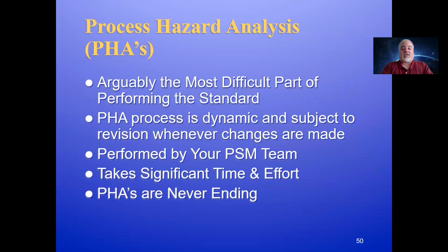Process hazard analysis. This is something that for refrigeration you don't have to worry about, because you don't have to go through and talk about what are the hazards of refrigeration. The hazard is a release, period, of anhydrous ammonia. The release is the hazard. And so you look at the facility layout, there's no surprise. If there's a release, you got a problem.